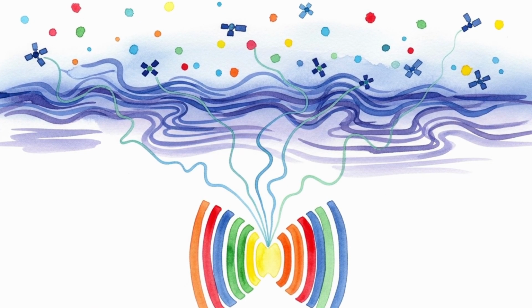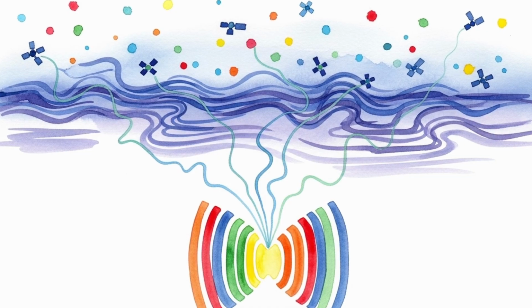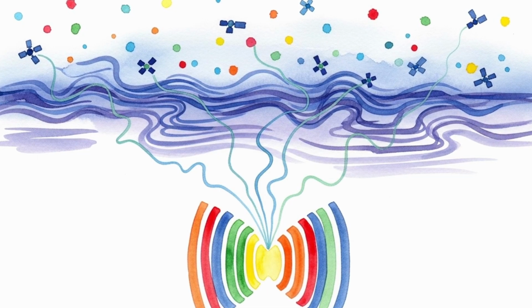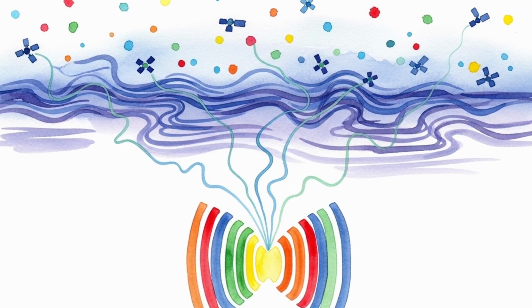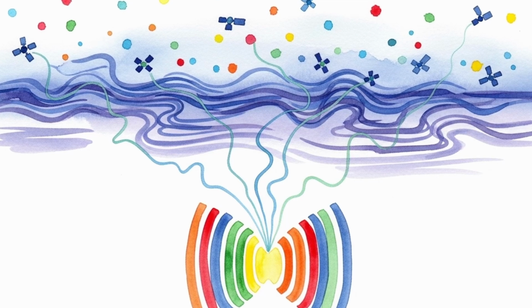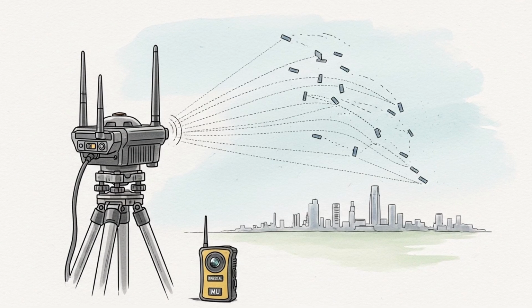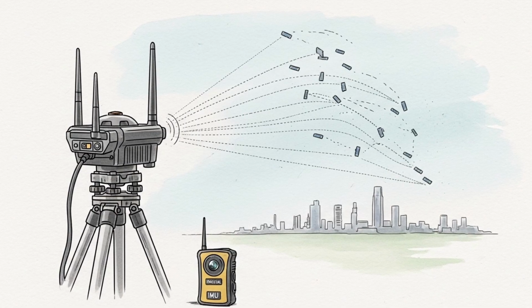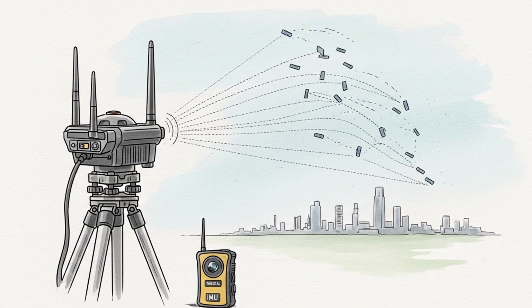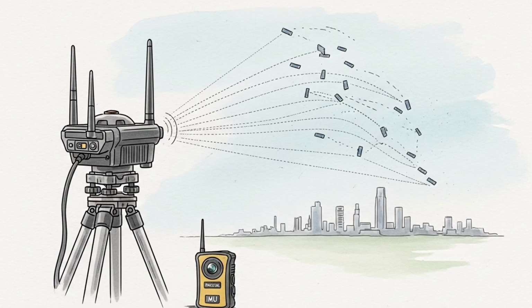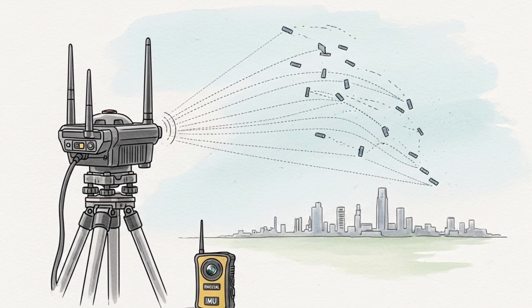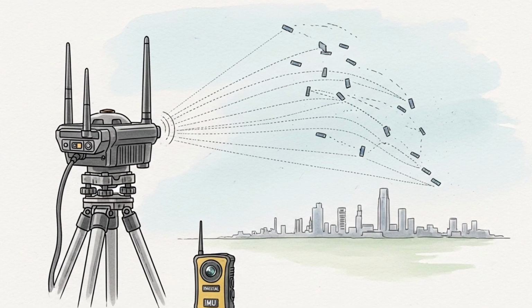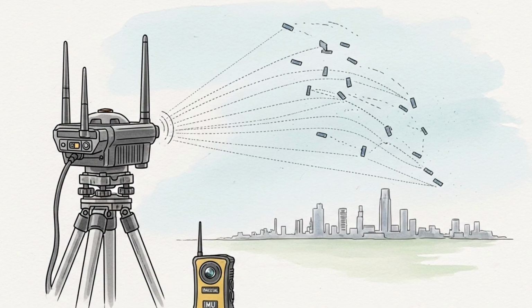Power transformers are stressed by direct current bias and partial saturation. Secondary effects include harmonics, reactive power swings, and relay misoperations. Pipelines and undersea cable power feeds also see induced effects. The storm unfolds in well-defined phases, and local spikes can matter as much as global indices for practical risk.